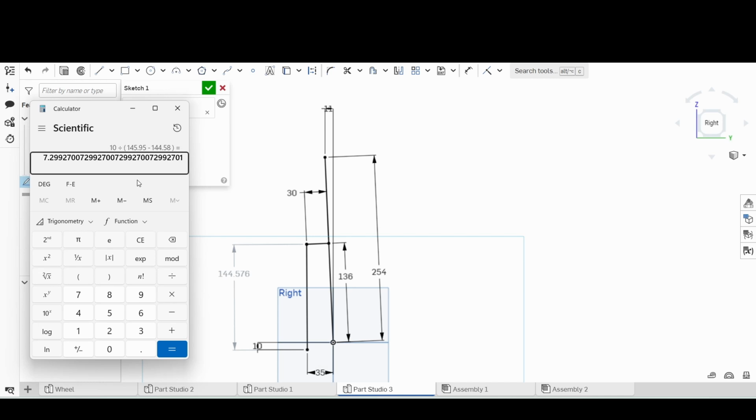So we get a pedal ratio here of 7.3 basically. And you can adjust your dimensions to get the pedal ratio that you're looking for. So that's like a graphical method to do in CAD if you don't feel like doing geometry, but either way works, and it's really for what's going to work best for you, what you need.